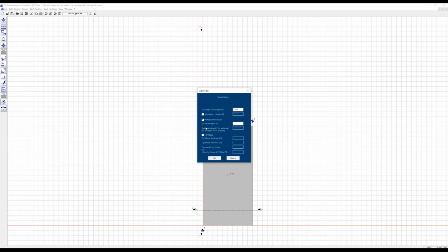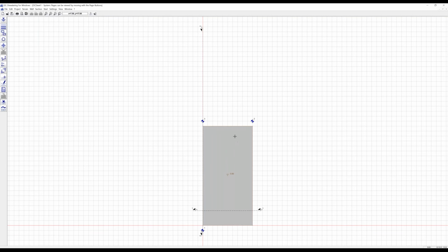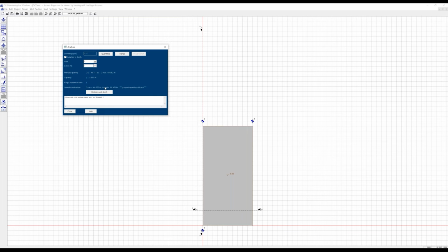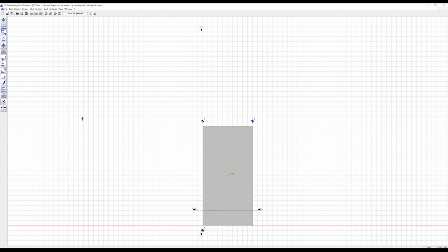So we have to go quite near to the aquitard to have a sufficient effect. So, for example, the enclosure should go to 60 meters, not to the aquitard of 18 meters, because in this case we would have no inflow at all. So down to 60 meters. First, if we calculate this situation, we have the same as before, because if the wells are outside of the foundation pit, this enclosure will not help us for the dewatering.